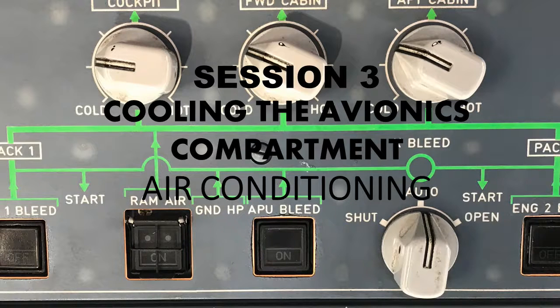So what does that mean? We're going to involve valves, and so certain valves are going to close, some are going to open. The question is which ones will be closing in this closed circuit. So with these conditions, the skin air inlet and outlet valves are going to close. If those are closing, what's going to open? It's going to be the bypass valve. Okay, this is the skin exchanger outlet bypass valve that opens under the two conditions I just mentioned. So remember, bypass and isolation kind of go together. The bypass valve and the isolation valve will both open under the closed circuit situation.